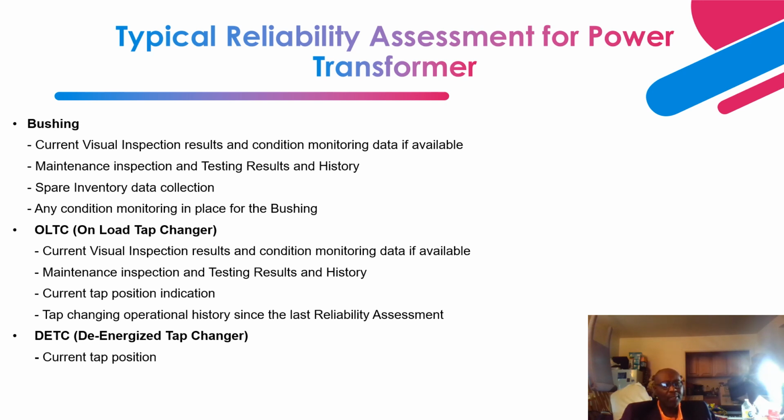So that is when you need to collaborate, check with your protection unit and other stakeholders, operations, maintenance, and have a meeting with them and bring to their attention what you have observed, and the need to adjust the bandwidth of the voltage regulator.